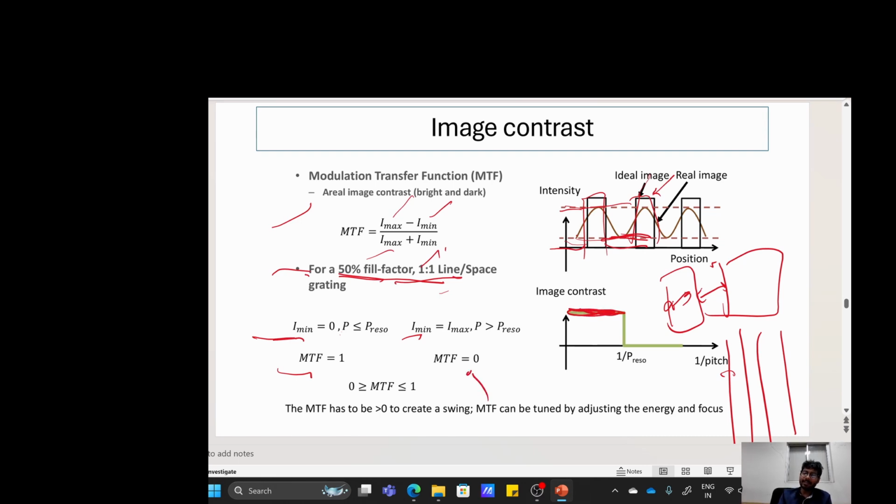There won't be any formation of the image on the wafer, because the intensity is the same everywhere. If the intensity is the same, there is no diffraction pattern on the photoresist, so it will either be completely dissolved or there won't be any dissolution.